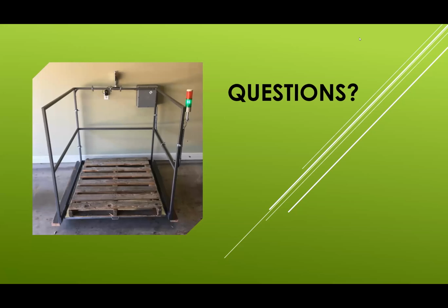Oh, great. Thanks for the input. From my experience in industry, I would recommend you look at drilling holes into the concrete and setting anchor bolts in an epoxy. That's typically how steel structures are attached to concrete. But overall, good project. Good job, guys. Thank you. There are 4 mounting holes currently present on the cage, so it is ready to be mounted to the floor.